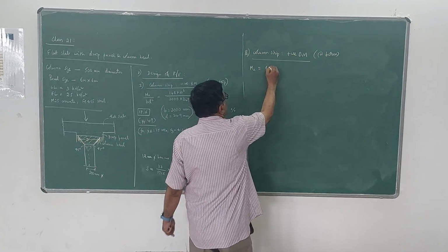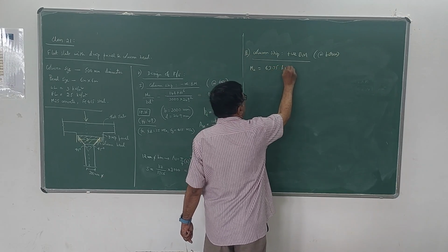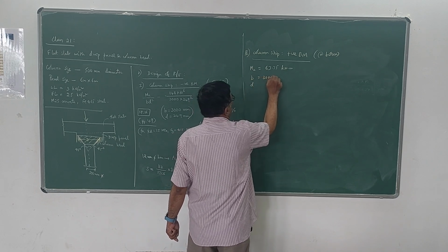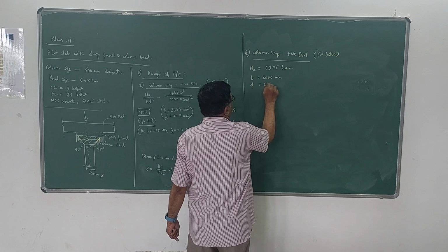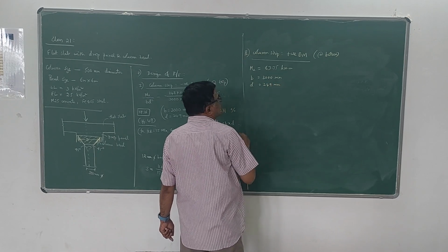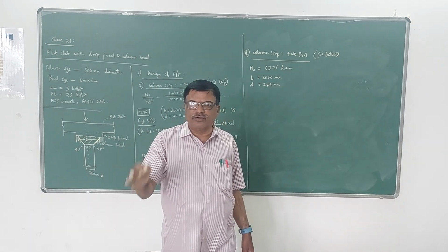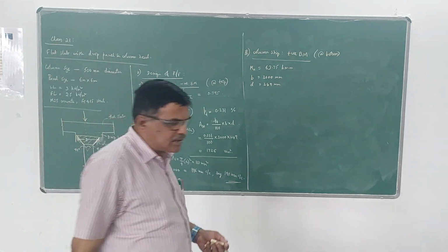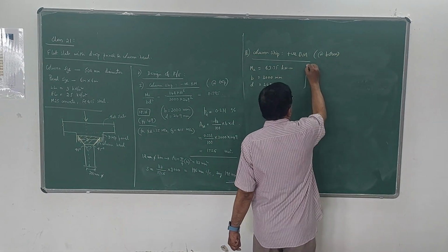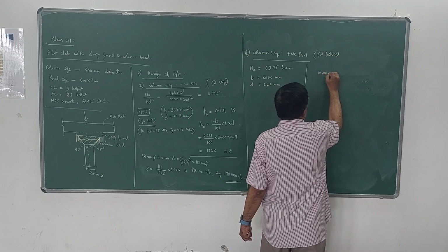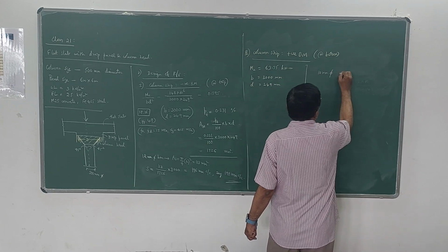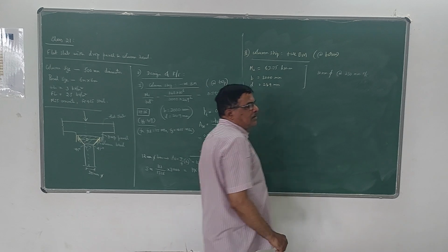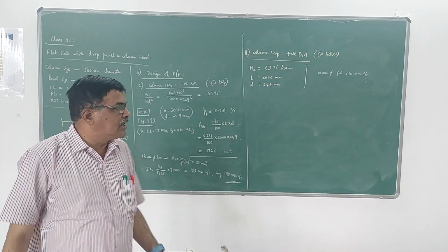63.75 kilonewton meter. And of course, your B and D values remain the same. B is 3000 mm, D is 249 mm. There is no change in that. So if you calculate MU by BD square and use the table, finally I will give 10 mm dia at 230. You can just check this. So AST, you can assume 10 mm because the moment is less, at 230 mm center to center. You can provide this. Next, what is the third one?